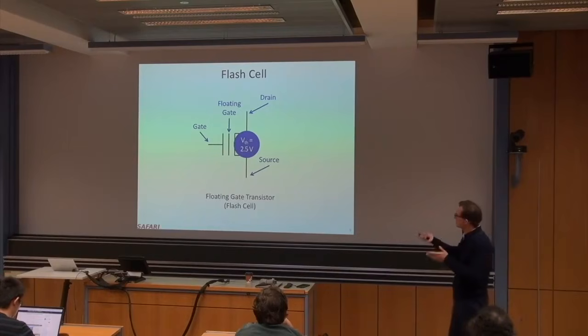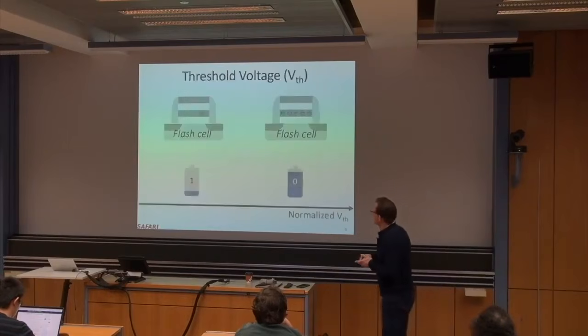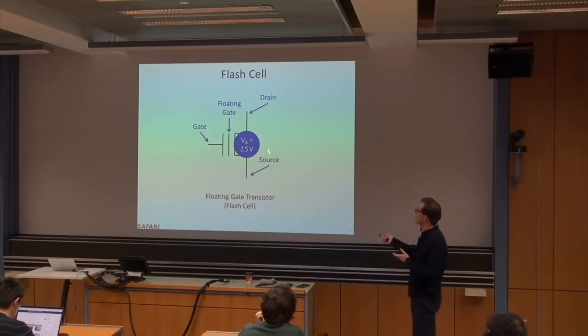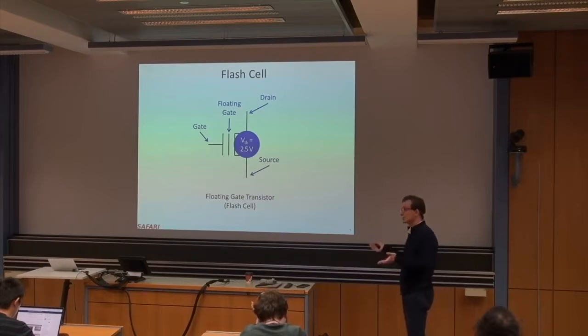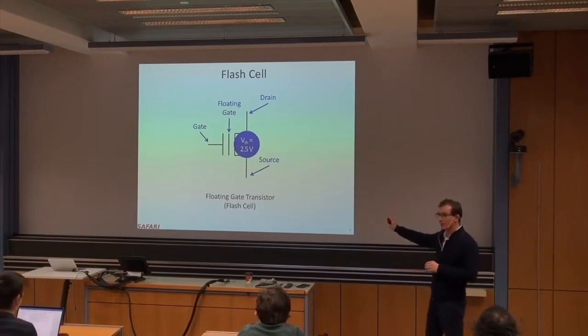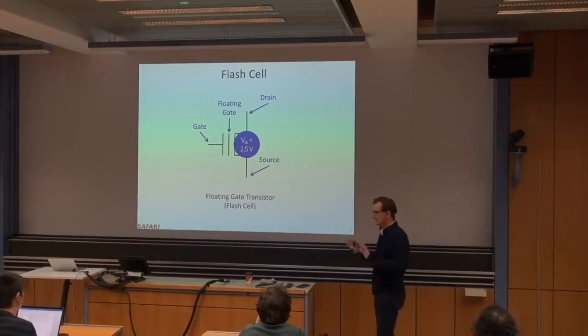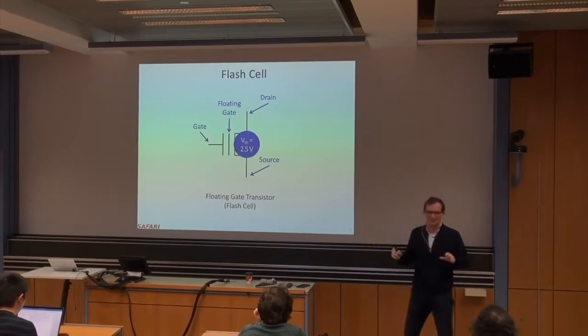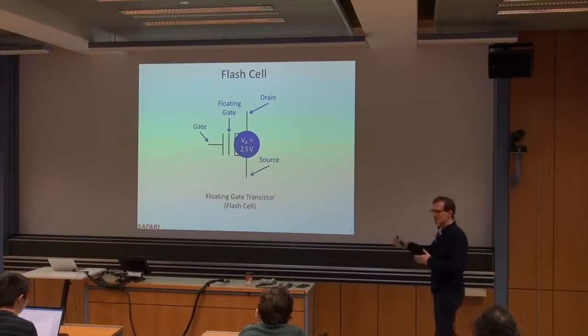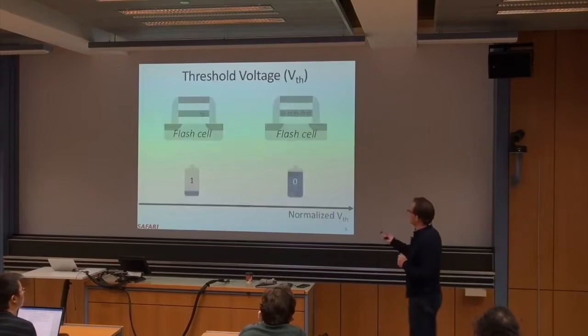So let's assume that the threshold voltage is 2.5 volts. When you program the threshold voltage and then apply some other reference voltage, the cell reacts in some way, depending on the voltage it's programmed to. So it can actually store the value forever. It's non-volatile, at least theoretically forever, of course. But in practice, you have a lot of other effects.